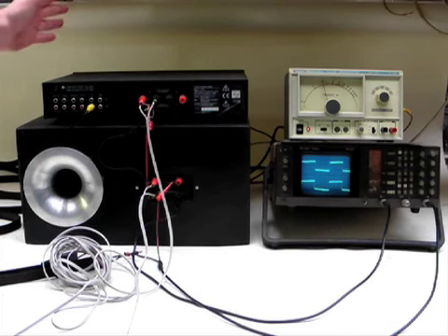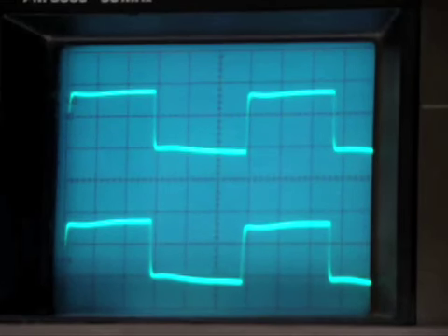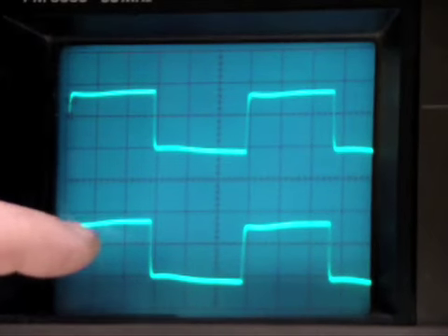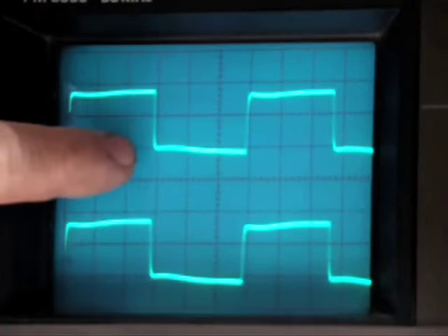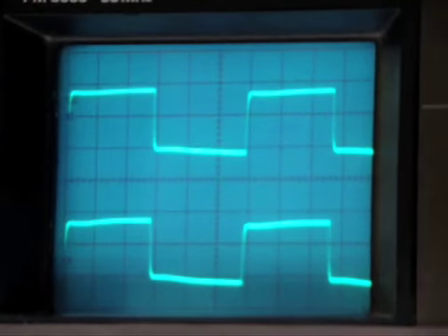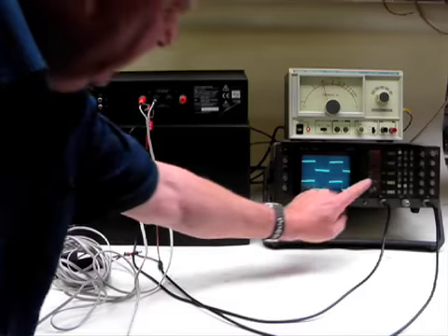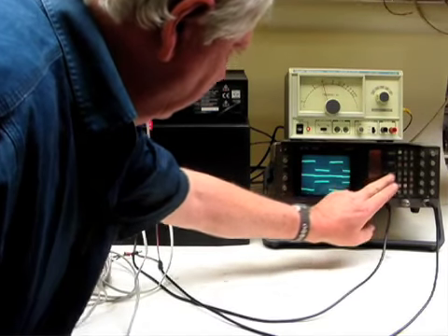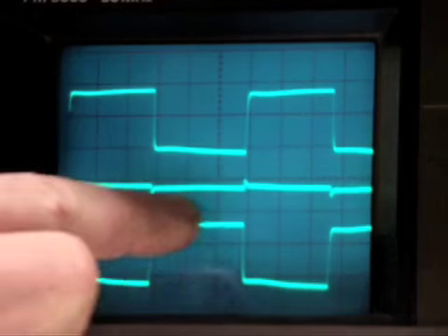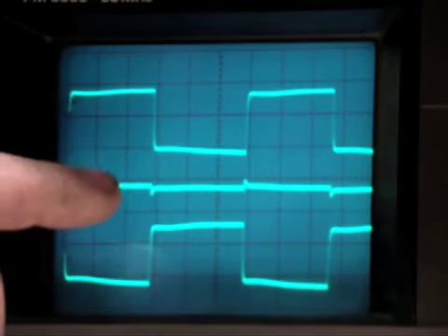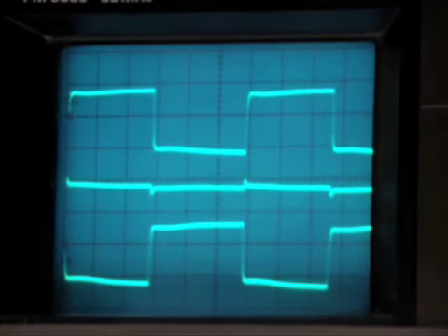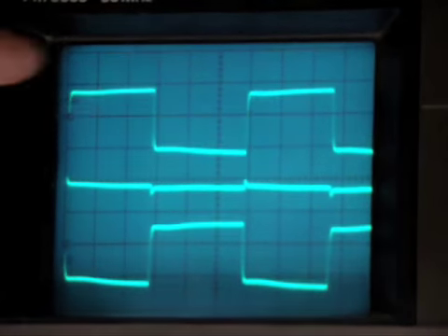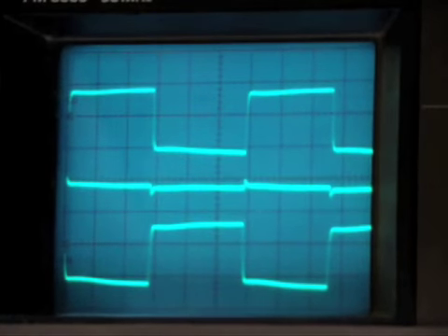and you can hear the tone from the square wave, and you can see the 2 beams here. Now if you look carefully you can see that the bottom beam is slightly distorted compared with the signal out of the amplifier, and if I press this button here, we've now inverted this bottom beam, and the function subtracts this beam from that beam. So what we get is the difference between the signal on the amplifier and the speaker. And you can see there you've got the little glitches.